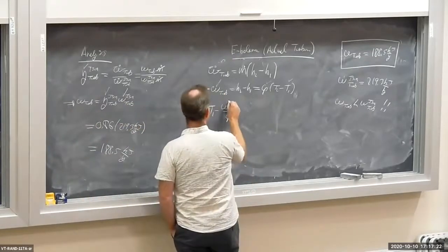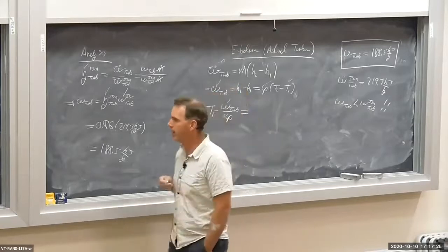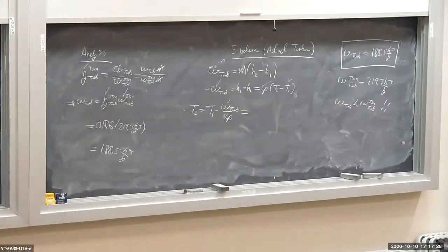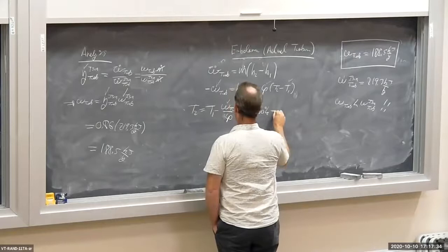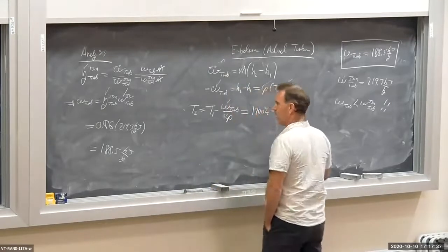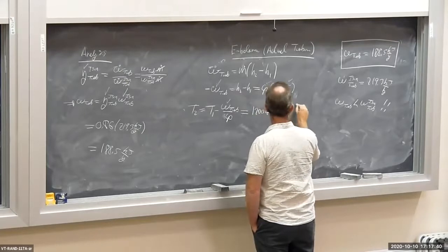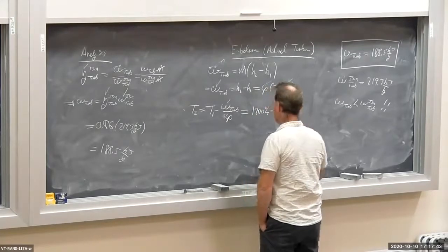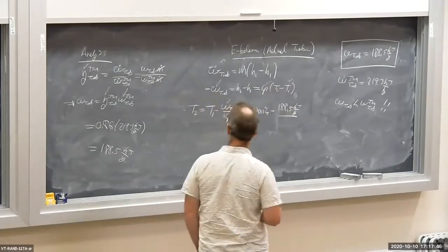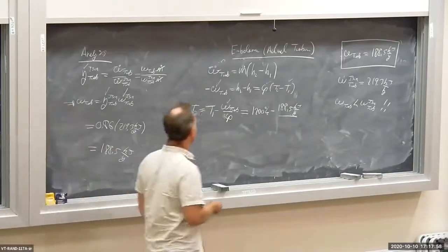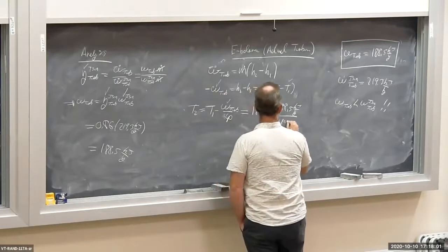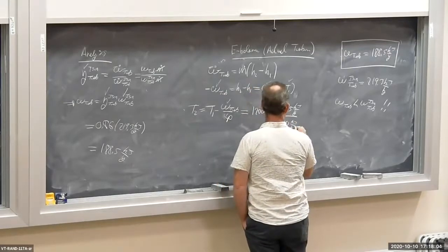All right, now I have W dot turbine, I have CP, and I have T1. Let's plug in. T1 is 1200 degrees Kelvin minus W turbine, 188.5 kilojoules per kilogram. CP, we already looked up. What was that? I guess I erased it. That was 1.142 kilojoules per kilogram degree Kelvin.